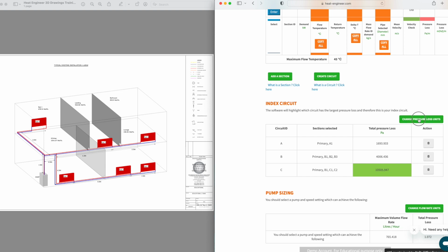or if we want to change those pressure losses, so 10.5 kPa. We know the smallest pump we can buy is around 40 kPa, so something along, I think there is a 30 kPa pump out there, but you can just see how massively oversized most of these pumps are, just for a standard 1-bedroom flat. Again, you can change any of these things to millimeters if you want, so it's just over a meter of head, as you can see, just there, which is the whole thing. So I prefer pascals, but then everybody can have their own view.